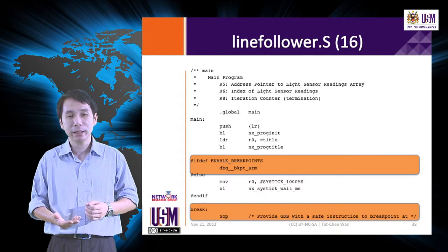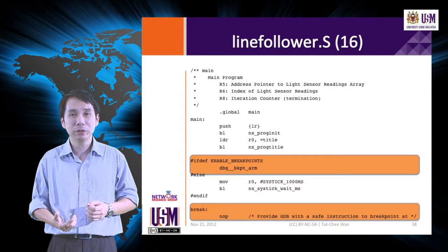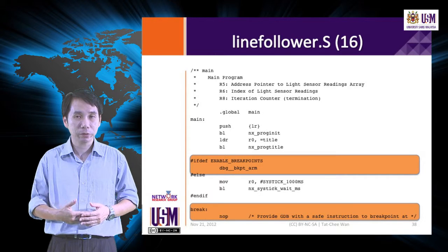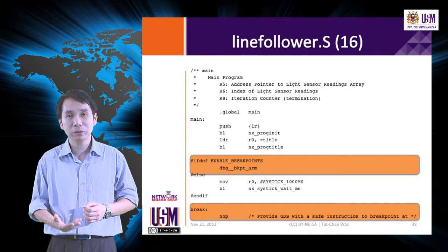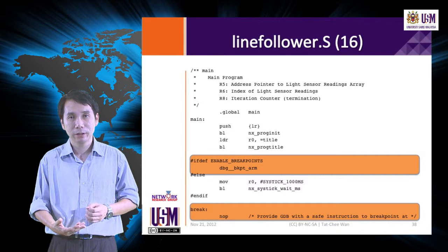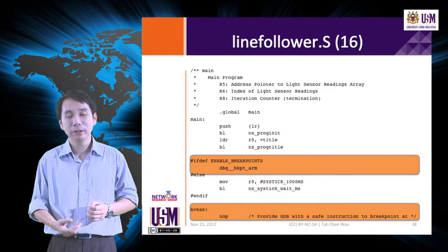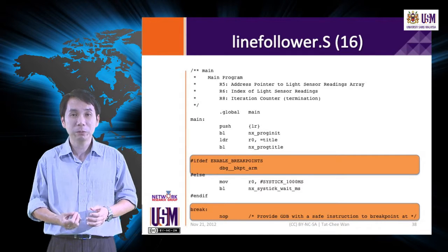Here we come to the main robot routines. Here we notice that there is an ifdef, which is using enable breakpoints to control whether we would pause the execution of the program to wait for a connection from the remote debugger when we are trying to develop this program. By default, an operating robot would turn off enable breakpoints so that it will continue execution without any stopping.